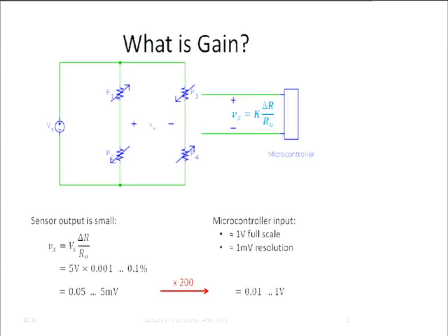But there is one problem, and that is that the voltage that comes out of the strain gauge is very small. It's millivolts. Now in the laboratory, you have this big digital voltmeter that has many, many digits and a big amplifier inside, and so for that instrument, it's not very hard to measure a few millivolts. Maybe the last few digits flicker, but basically it can do that. But it costs $1,000, and for the kitchen scale, that wouldn't be exactly the right solution.